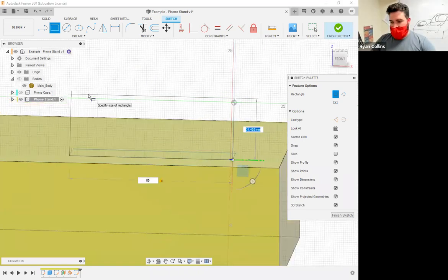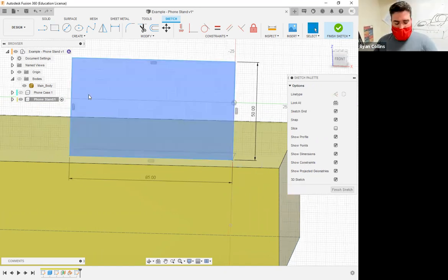And I want to actually have this disc nested into that. So I got to make sure I measure that. I'm going to have to actually expand this because this disc is wider than that base, but that's okay for now. So it is 100 millimeters wide. I'm going to want this to kind of nest right in the center. So let's start by, I'll just make it 50 tall, because the rest is going to be nested down inside. Okay, great.